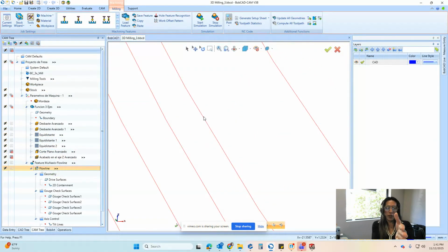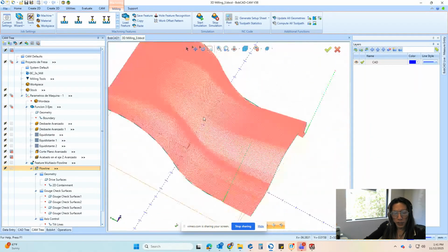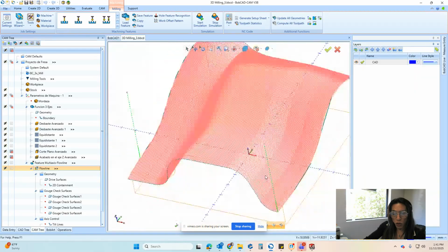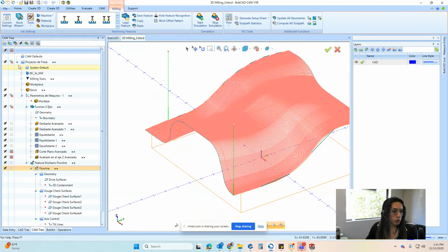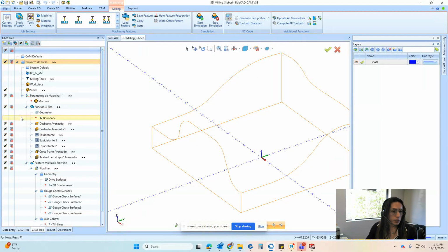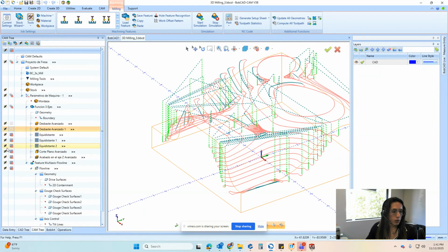It's just that the toolpath understands and raises itself above the other step. So it gives you this type of finishing. And again, you have the control of extending the toolpath. So if we were able to compare, let's just do the rough and pre-finish and the equidistance.